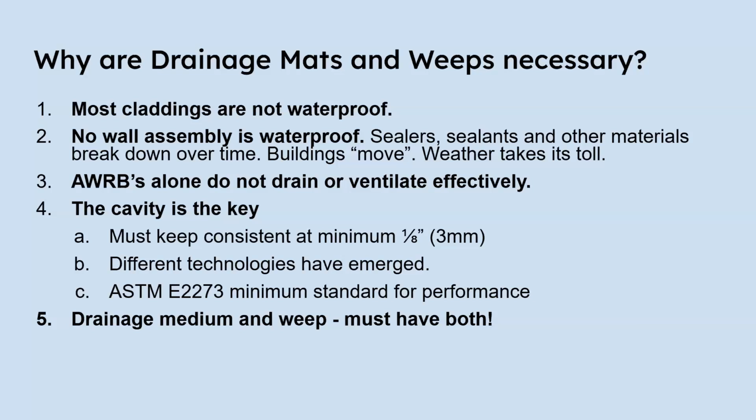It's simply reality. Buildings are also not maintained as well as they're intended to be maintained, or as frequently as they're intended to be maintained. Sealants aren't repaired or replaced, and so claddings essentially become not waterproof. And in reality, no wall assembly is waterproof. And if it is initially, it doesn't stay that way for very long.